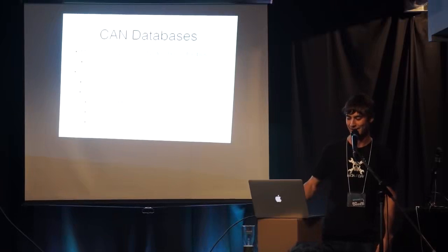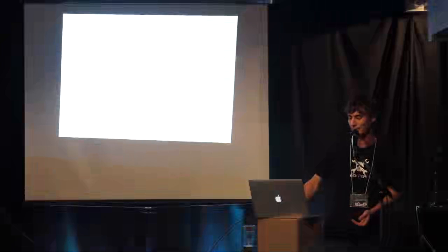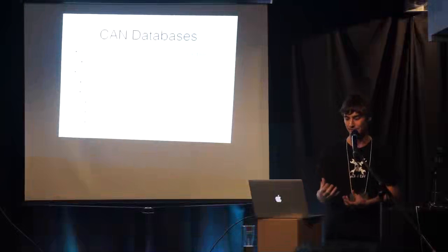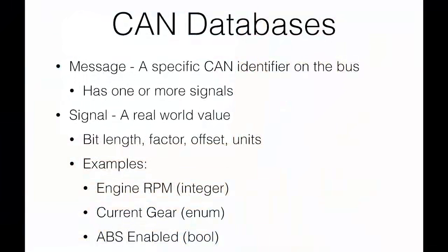Let's say, in this big list, I'll pick one: 0x6ED is the identifier I want to look at. Now, whenever I get that message, I know it has some meaning. I will decode it into its signals, which say what each bit in that message means. It'll pack them together into data types like floats or signed and unsigned integers, and it'll just decode it.